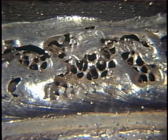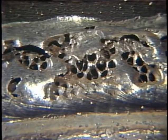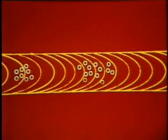The next type of discontinuity is porosity, which is best described as gas entrapment cavities formed during solidification of the weld. They can appear in various forms, scattered uniformly throughout the weld, or grouped into clusters at specific points.